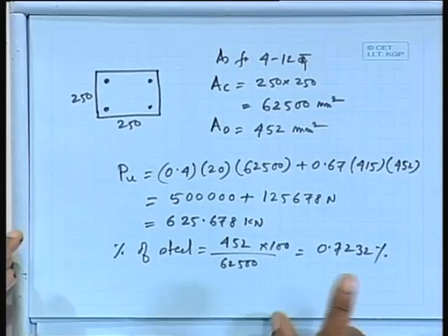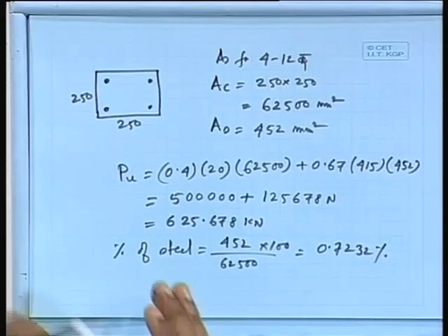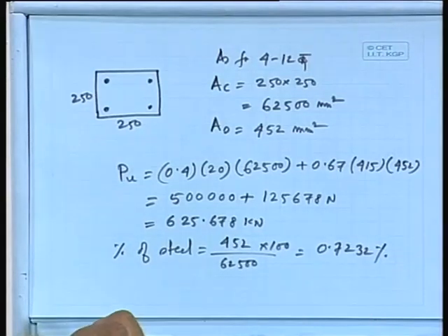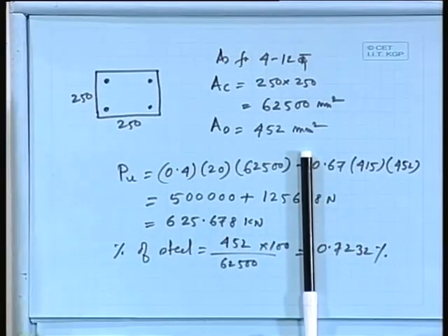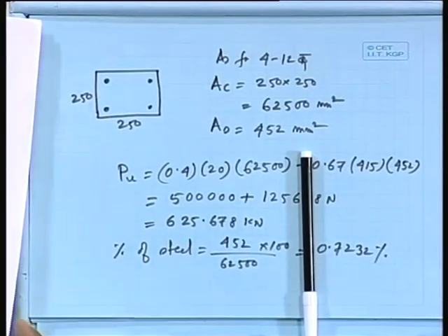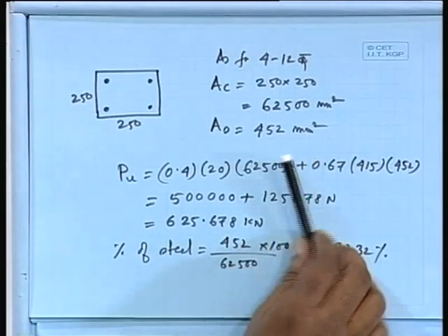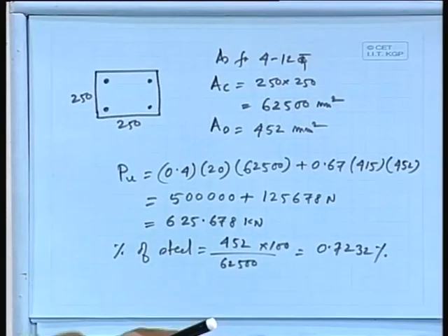Generally, what I mean to say here, most of the cases you will find out this is a very, very standard practice that mason, all those things in general building, what they do is 250 by 250 and use 4 number of 12 bars. But according to IS code, even in that case, it is very less, the value that is less than 0.8. So, we have to follow those codes, because it is very, very important.